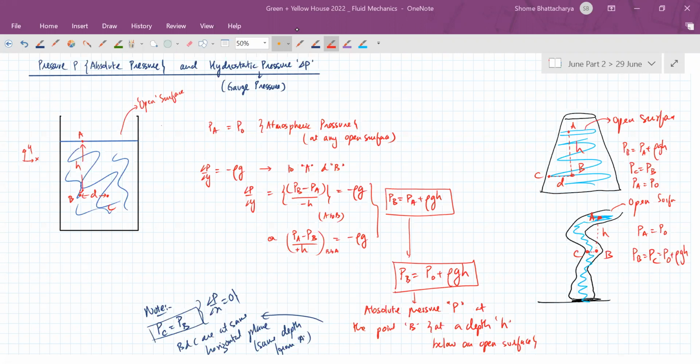Or we could have taken a three-dimensional shape like a cuboid and considered all the forces together. Then the horizontal forces would also have to be divided into two components, X and Z, but you would see again they would balance each other. So the six faces of the cube would be in two pairs cancelling each other, but the vertical ones won't be cancelling. Always the below surface is experiencing more force due to pressure compared to the upper surface because it has to balance the weight. So that is what shows us that gravity creates the vertical pressure gradient. And because there is no equivalent of gravity along the X or Z axis, there is no pressure gradient.